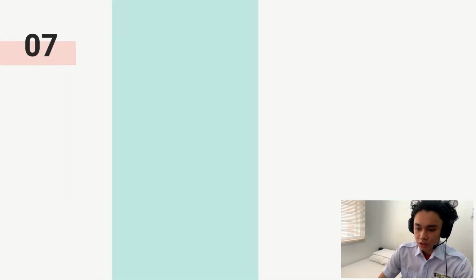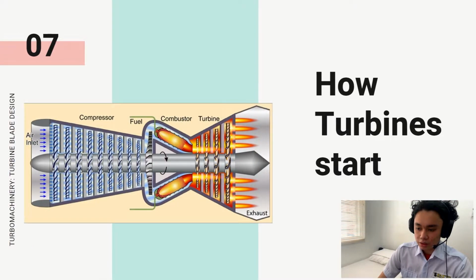Through activating the APU, electrical power of the aircraft will be turned on at the same time powering the AEC. The AEC then takes over the entire engine to start its operation, sending pneumatic pressure from the APU to the accessory gearbox which rotates the N2 shaft. As N2 rises, airflow will be established in the system causing the engine to enter standby mode since the intake fan and compressor is connected to a single shaft along with the turbine which passively supplies a percentage of its power to the fan and compressor.